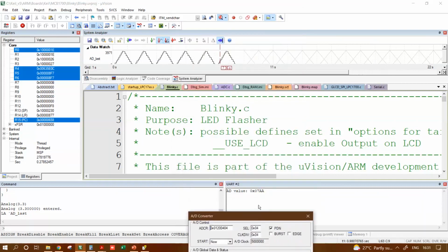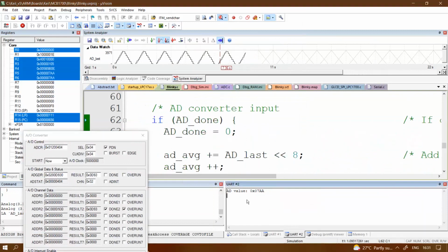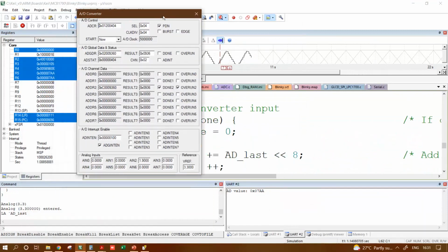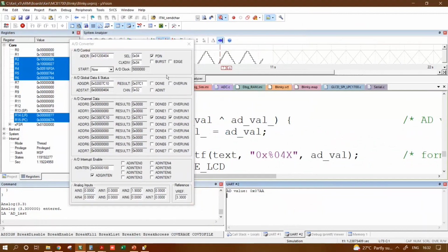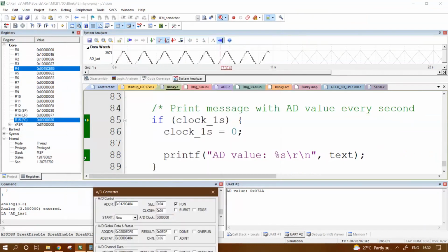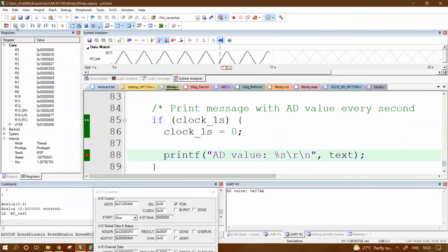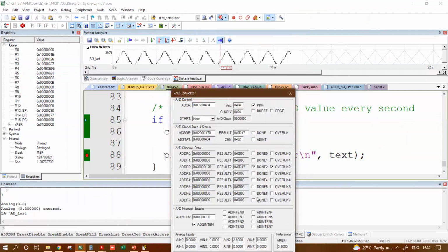We don't have a sample application, I'm just trying to show you here. Do you see the ADC value printed? Or maybe we can see that by putting a breakpoint here. ADC is triggered, and you are seeing ADC has already started printing.